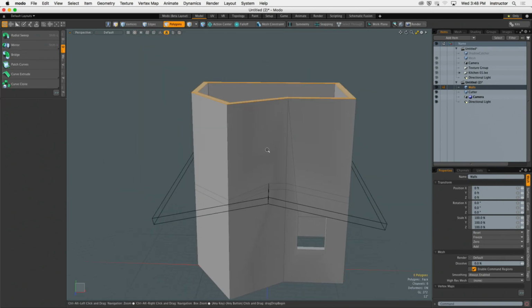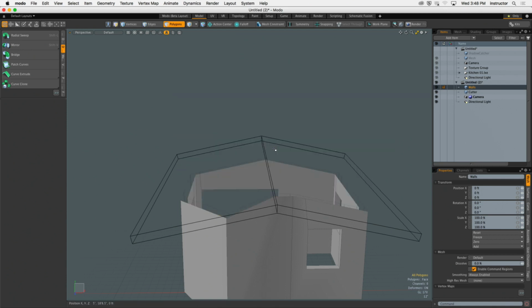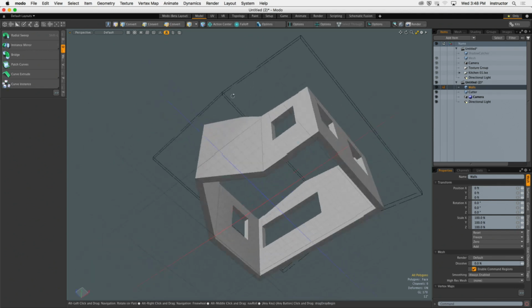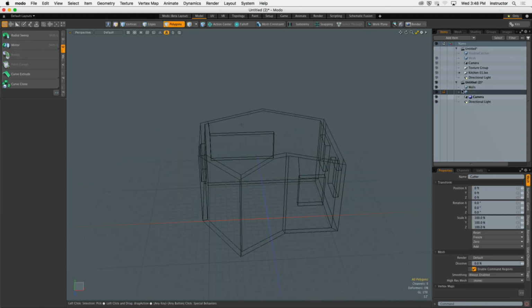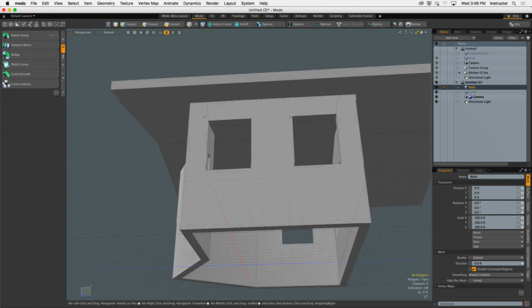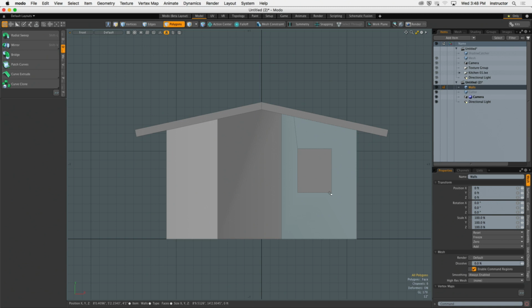Now there's some junk in here that we don't need. I'm going to delete the top portion of my house. Just hold down the Shift key and up arrow. Delete all those polygons. They're not needed. And now my walls perfectly match the slope of my roof. Okay? Let's get everything back into one layer by cutting and pasting. And there she blows. Starting to look pretty great. This is the power of Booleans, taking one piece of geometry and using it to slice and edit another piece of geometry.